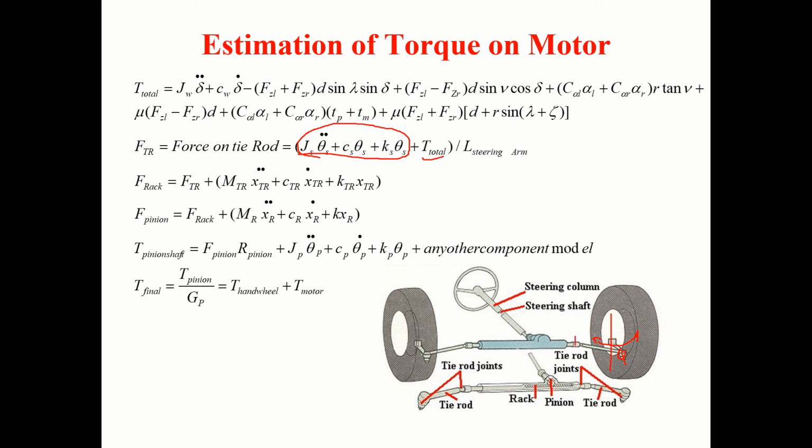Then what is the force at the rack? The force on tie rod plus this dynamics, tie rod dynamics, that I have considered. Then finally, what is the force on the pinion? I have considered this force plus this dynamics, linear dynamics.